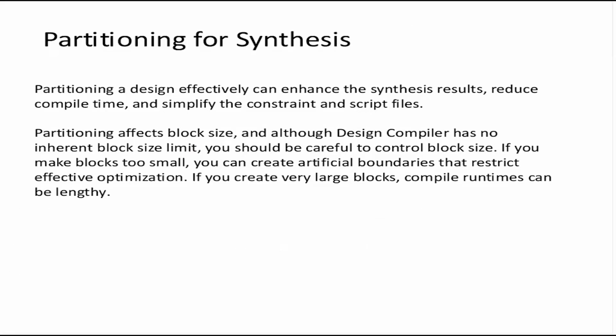Now let's talk about a very important concept called partitioning for synthesis. What does partitioning mean? Partitioning means dividing your design according to different design goals such that it aids synthesis and in turn aids performance and area. The metric here can be that, let's say, a big complex design is taking a lot of time in synthesis. What you could do is partition it into smaller designs and synthesize them separately to save on runtime. Thus, it might also help you in terms of performance.